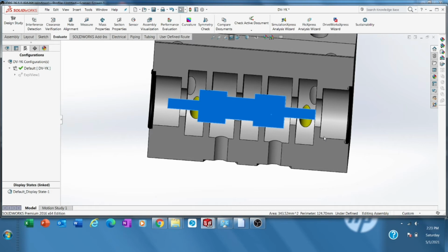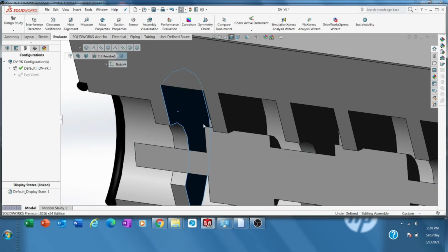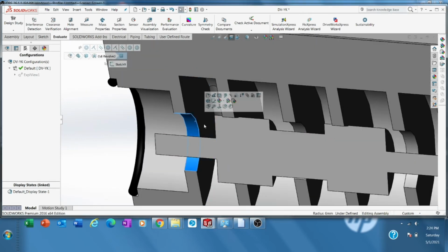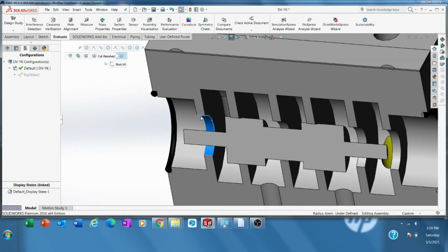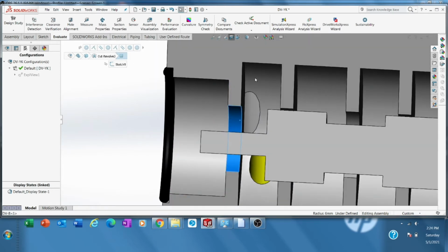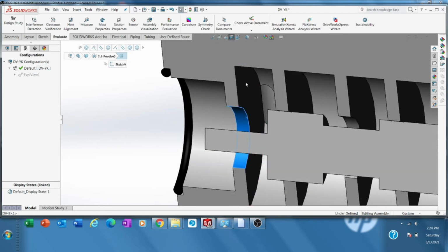But if we are very familiar with machining and have experience with lugs, drilling, and so on, or from university times, it's not possible to make a room like this by machining, because we have an undercut. How would tools go into this room and cut this, and then when they move back hit this wall? Impossible.